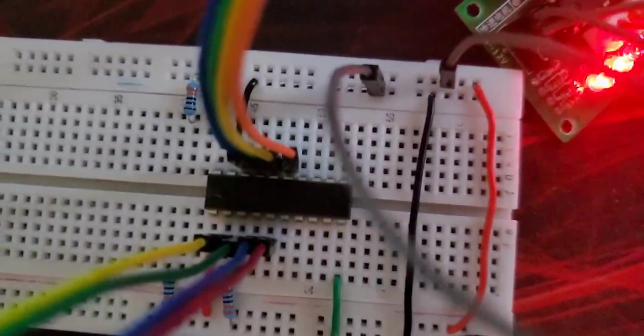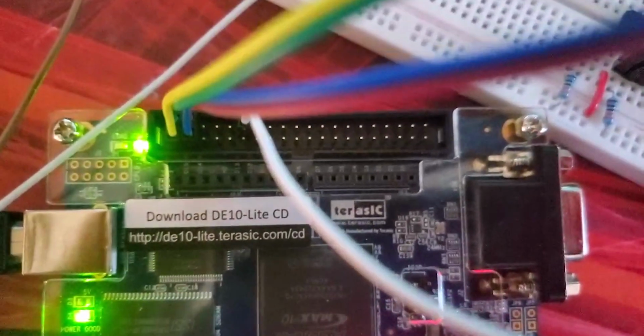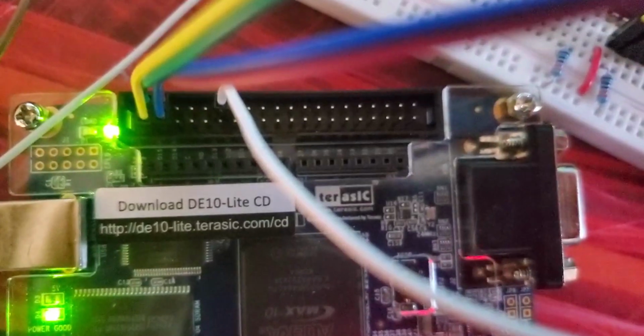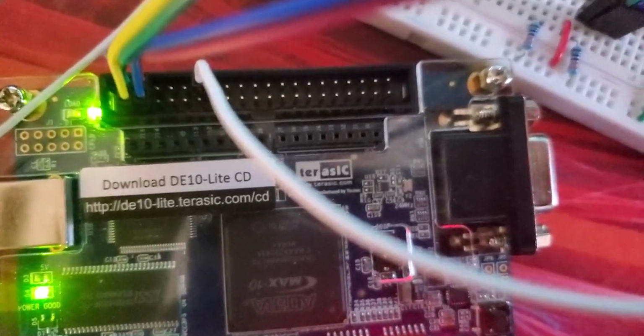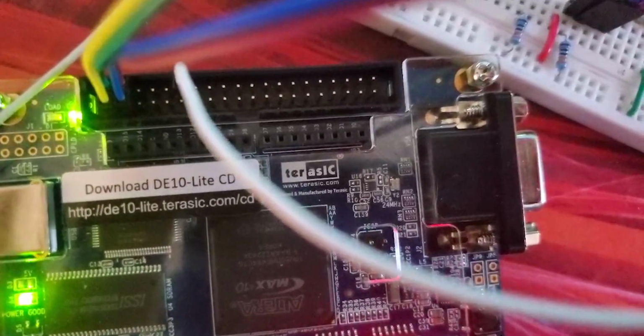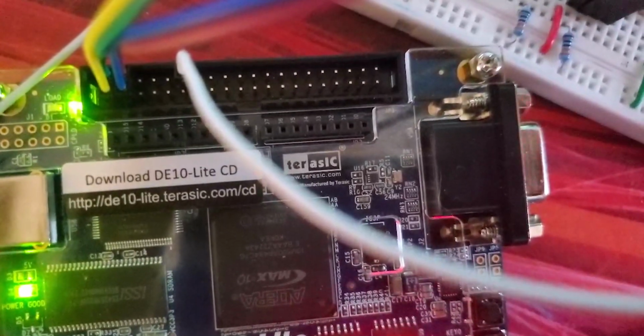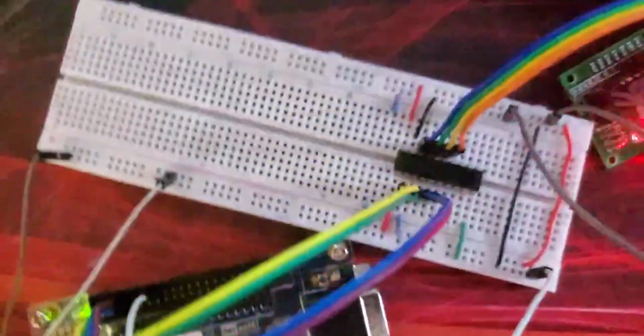So the materials we were using are a 245 buffer. Those are the connections. We are connecting the GPIOs of the FPGA. We're using the outputs 0, 1, 2, and 3. Those are the first ones in the pin planner. And that cable, that white cable right there, is the GND, and that's pin 12, I think, of the FPGA. So we have common GNDs here.